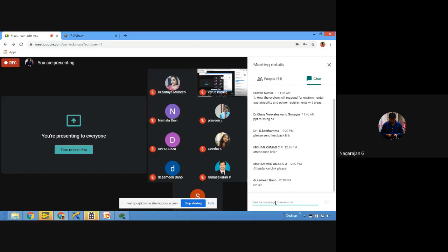Okay, so this is the introduction to the hardware. Next step is we are going to learn how we can develop a small application using this NI-RIO based hardware. So I'm going to use a hardware called NI-MyRIO. If you want to work with the hardware, in your system you should have installed LabVIEW software and the respective RIO drivers. The NI-MyRIO driver should be installed.